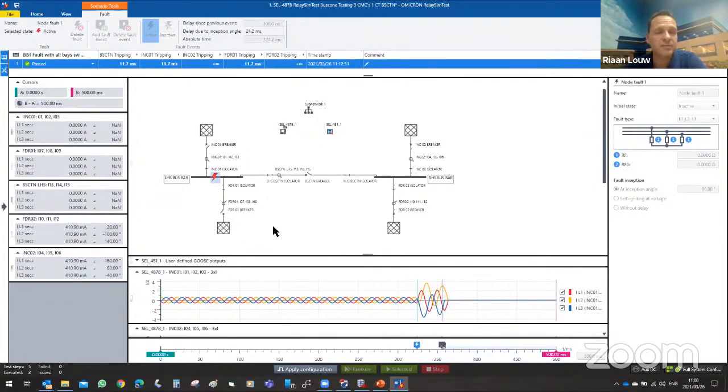This is the case because I'm simulating all these disconnectors and breakers via the GOOSE, so the whole system can at any given time know what has been published, what has been received, and simulate this whole system according to that. Now, look at the pass and fail assessments up here.